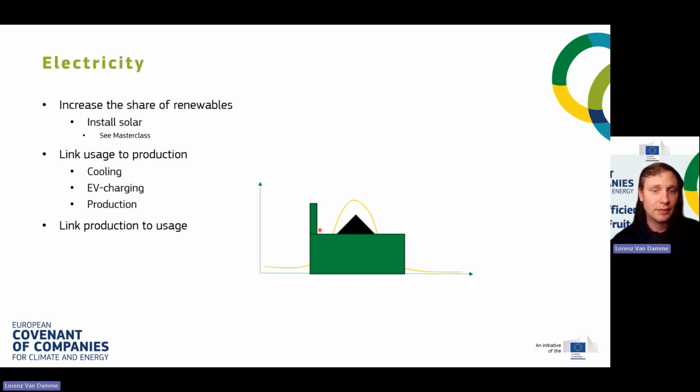Here, the very quick win is quite obviously to move this production spike to around noon, when we have the most solar production, and that way we can make sure that we optimize our solar usage. We see that the EV charging is still present here, but will stop during this production spike as well, as we have also seen during the previous example.